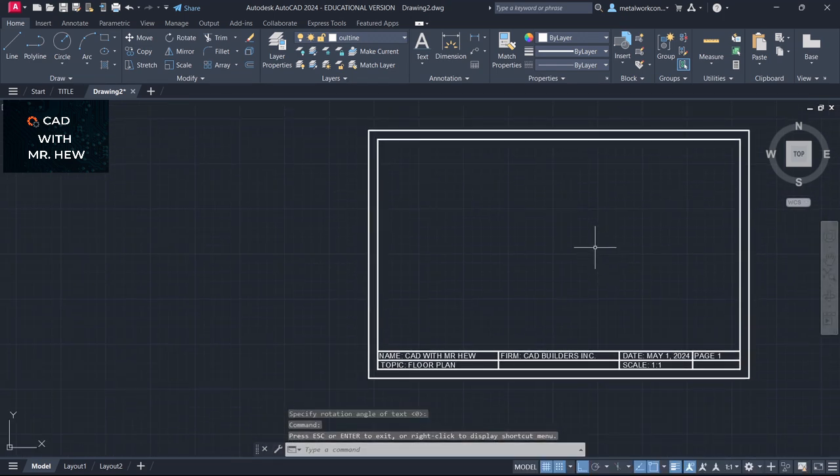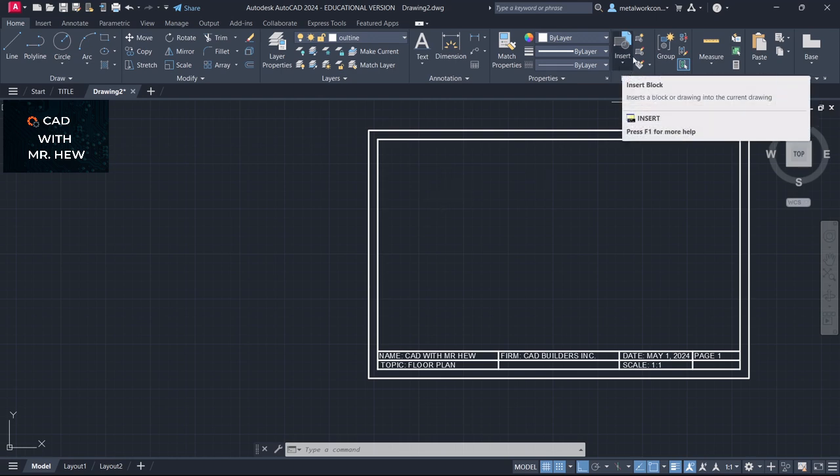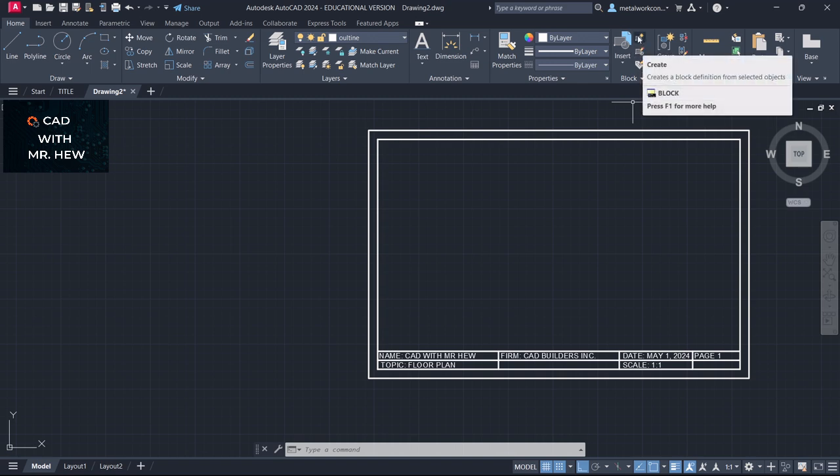All right. So having completed the title block now, the next thing we're gonna do, we're gonna save the title block as one entity so that when we import it, it comes in as one entity. Now you could have saved the title block without the information which I typed in. It's up to you. All right. If you wanted to save like a blank sheet.